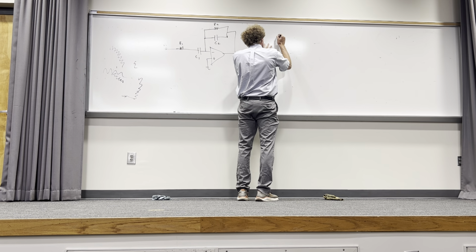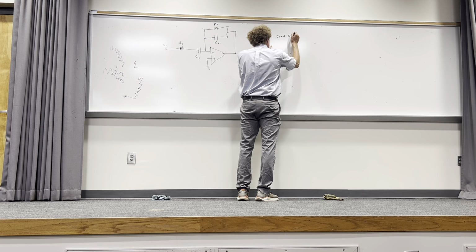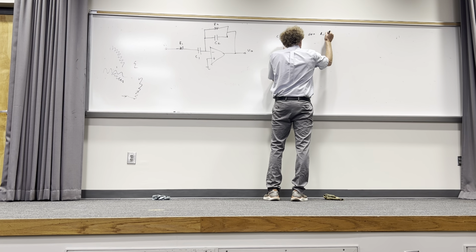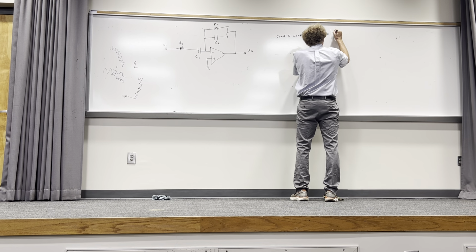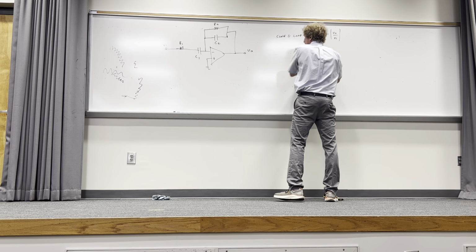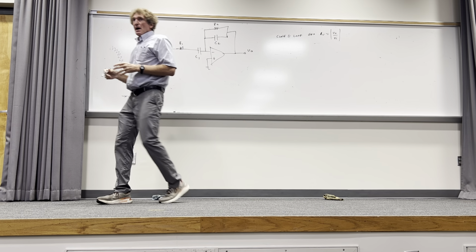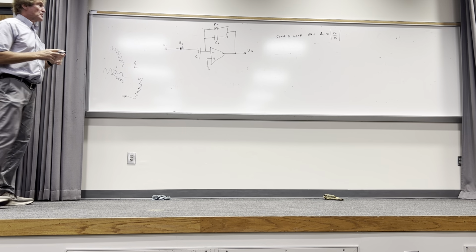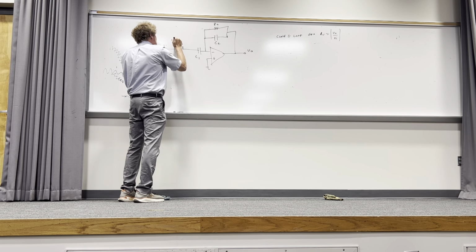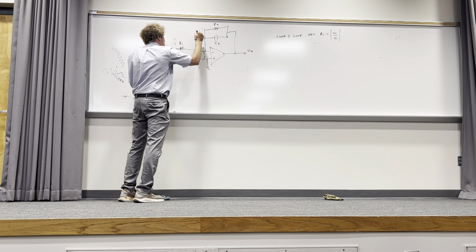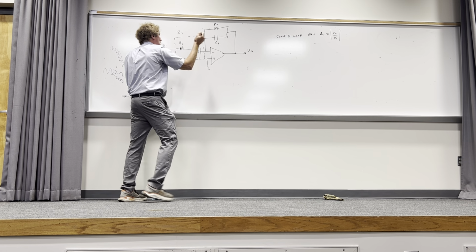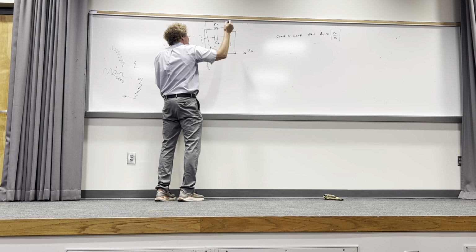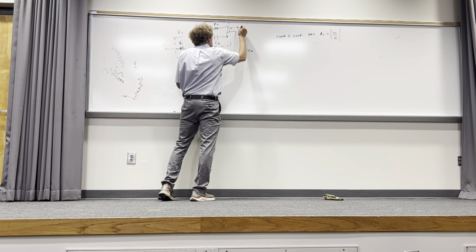be, this is the closed loop gain. And I'll just put a magnitude here of V out over V in. That's what they want. So now, and this is the way I'd recommend you think about this problem, I'm going to do it in two block forms. I'll call this, whatever the impedance of this is, Z1, and I'll call this impedance, that is between the negative terminal, or the input and the output, simply Z2.